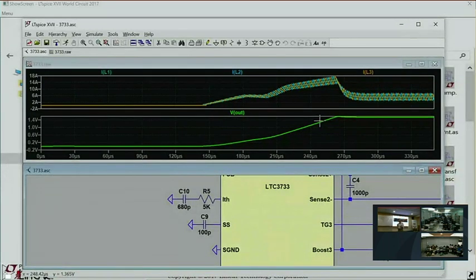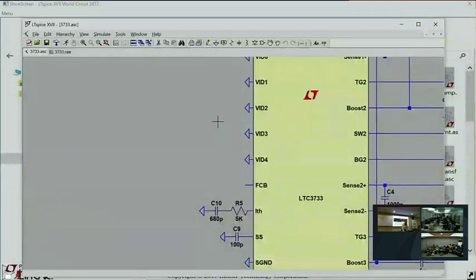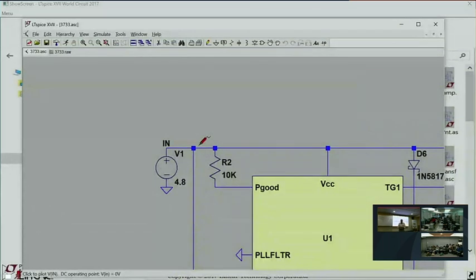So basically, to convert a jig circuit to a reference design, you have to audit the value of the capacitances in the circuit. You have to find the one that probably is too low in value. It would be the soft start cap is too small. And there is one capacitor that is required that is missing. The capacitor that is missing is the input filter cap. See, you have to bypass. You don't just need an output filter cap. You don't just need this capacitor here. You have to filter the input.